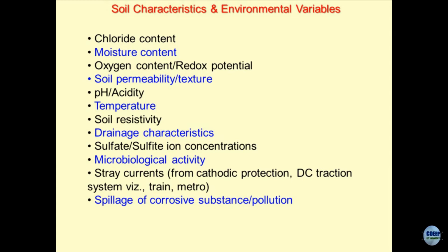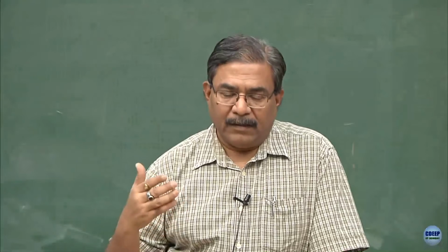The texture of the soil is described by a sort of USBR classification system, alright, and from there I can make out whether the soil is clayey or sandy or silty, and accordingly we can link the texture with the air permeability, or the gases which are getting formed inside the soil mass, and when it comes in contact with, let us say, buried utilities which are at elevated temperature.